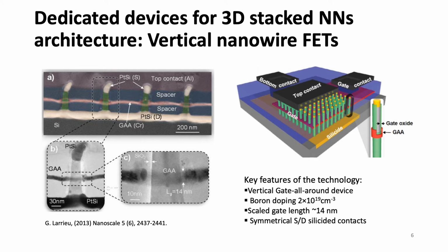The technology features nanowire diameters ranging from 22 nanometers up to 50 nanometers with 60 to 625 parallel nanowires. The threshold voltage ranges from minus 0.2 to minus 0.5 volt. In addition, the subthreshold behavior of the transistor exhibits a 50 to 70 millivolt per decade subthreshold swing for nanowire diameters smaller than 40 nanometers.